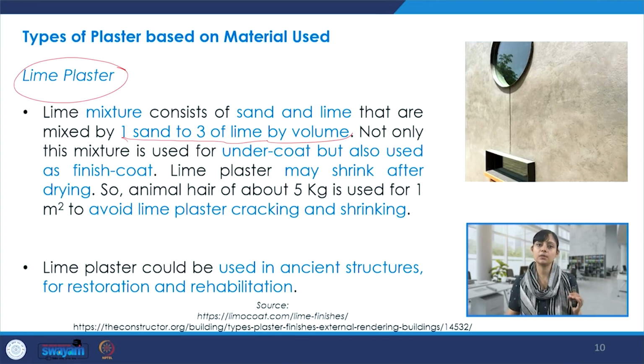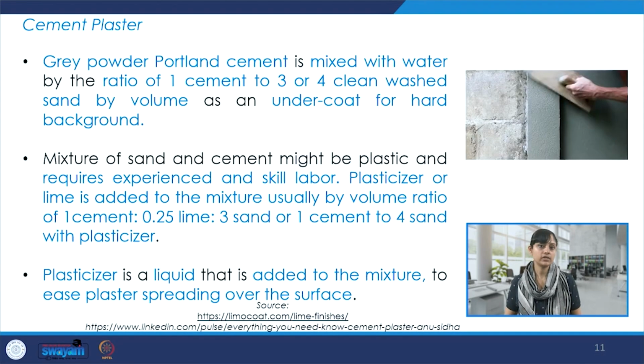The issue is that lime plaster may shrink after drying, and we have to avoid this cracking and shrinking and drying of that plaster. And it is very, very popularly known to have been used in ancient structures, especially. And it has a very good life and it looks very nice. But yeah, these days we don't do much of lime plaster because it's also time consuming and it requires certain skills.